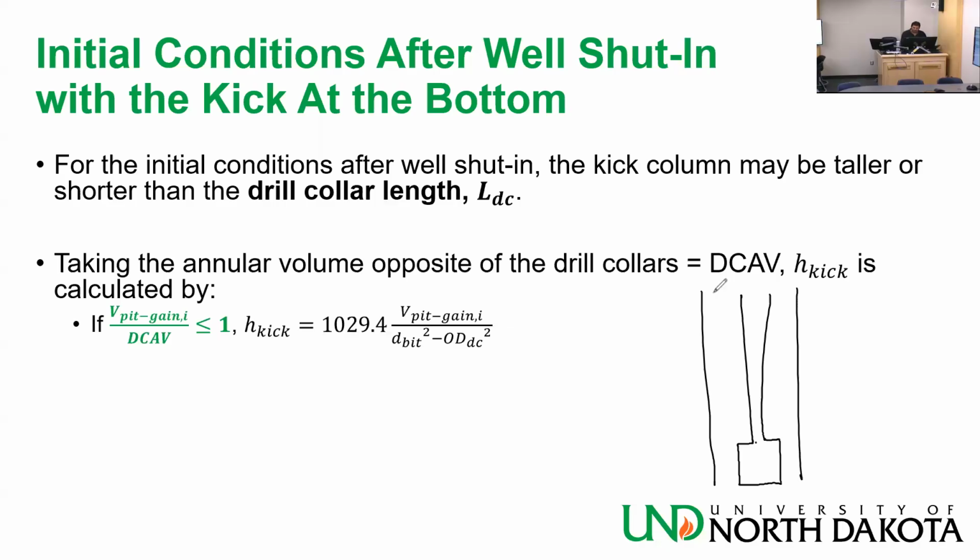If I'm in a situation like this, look at how big my kick, how tall my kick is. My kick doesn't exceed the drill collar length. Okay, my drill collar length is this much. This is LDC.